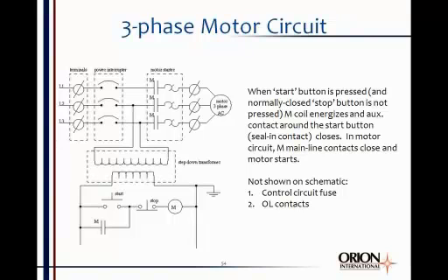Now, three-phase motor circuits. You see a schematic of one here, and typically what you'll do is follow the power through first. Here's L1 through a power interrupter. That'll be a breaker or a fuse. Let's assume it's a three-phase circuit breaker. Okay, to the main contacts in the starter, through the overload heaters, and to the motor. Each phase goes through the circuit breaker, to the main contacts, to the overload heaters, to the motor.